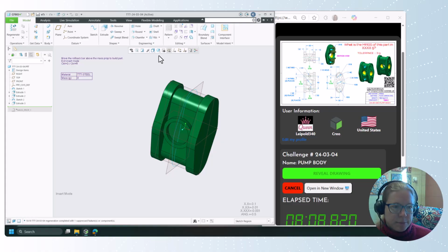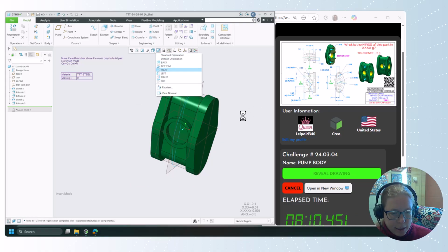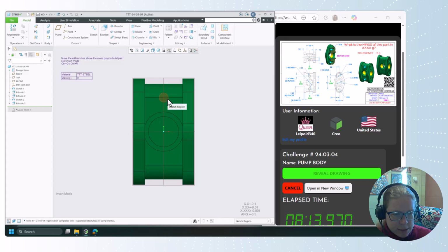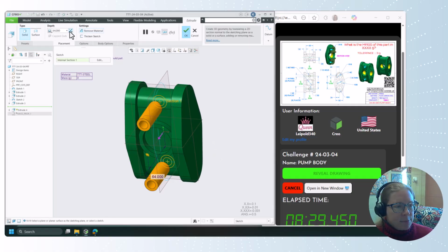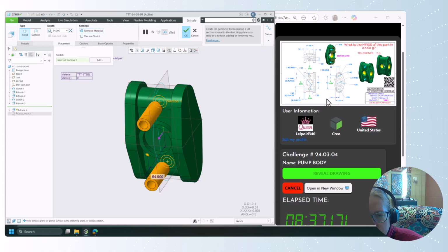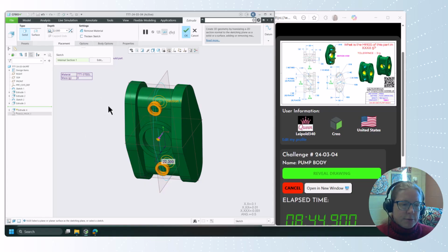Then if I go back to my front view, and I'm looking for the hole, let's see here, right there. Again, a right click will kind of do a quick cycle. And then I'm going to hold down Control and get the other one. We'll extrude those. Those are also going to add material, but those are only going to be one-sided, right? You can see it in the section view that it doesn't go out the back. The depth of those is 22, which is shown in this side view at the top. So those are just going to come forward with that depth of 22.